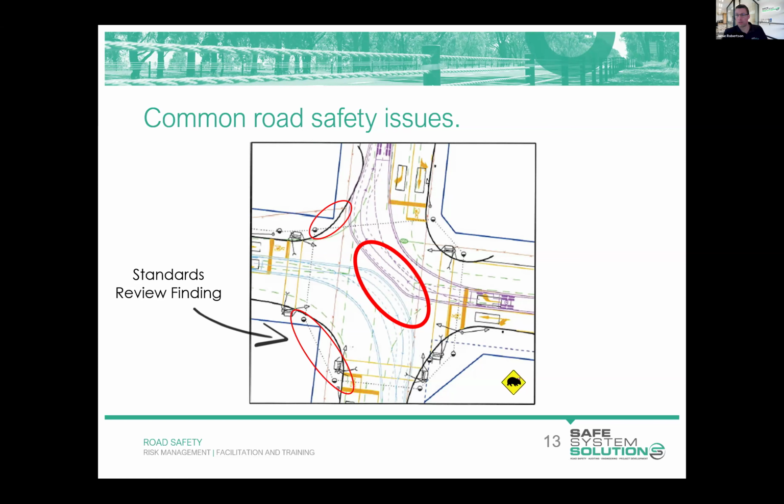Vehicles cutting across those areas that they shouldn't, even more. So yeah, it's for the auditor then to weigh up the risks associated with the issue that we've identified around swept paths. Yeah, that's right. And the reality is that auditors are often pulled in these sorts of situations where we have big constraints in available land, and you've got particular vehicles, and the developer and possibly the road authority are trying to understand the risk profile and then what possible ways this can be mitigated in a reasonable way.